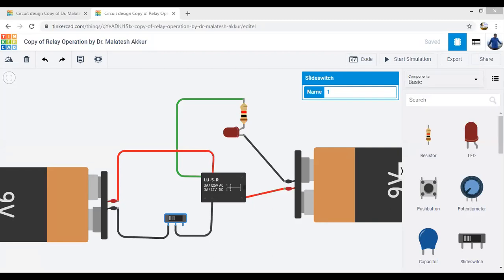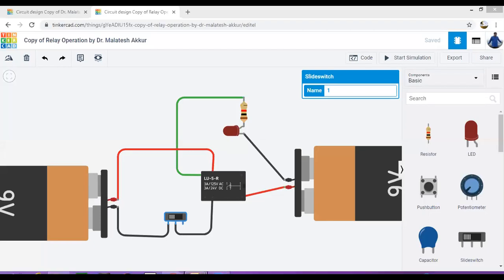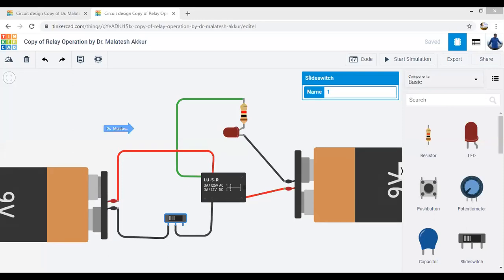Now let us have a look at the sensor. Here I'm going to use the HC-SR04. It has 4 terminals. As usual, one is VCC and one is the ground, and 2 more terminals. VCC is where we can apply 5 volts, and this is ground, which is the negative terminal of the circuit.